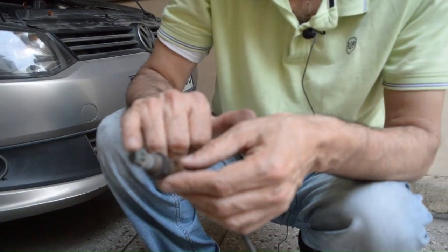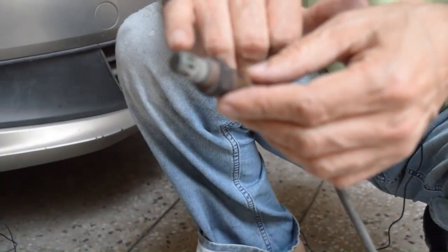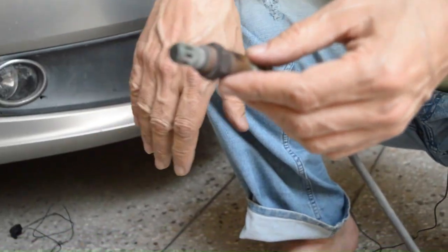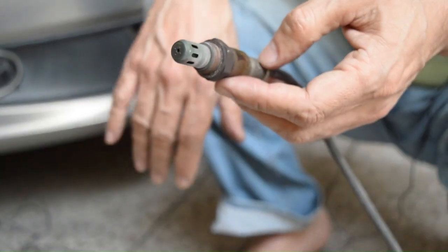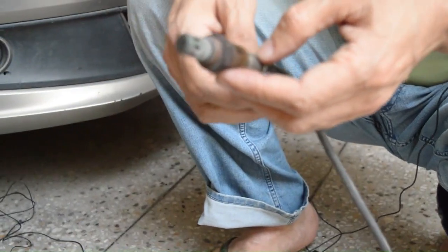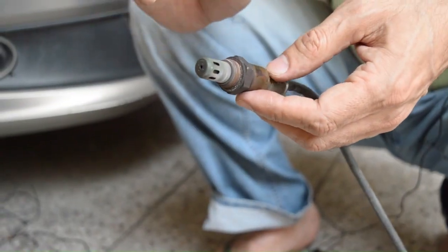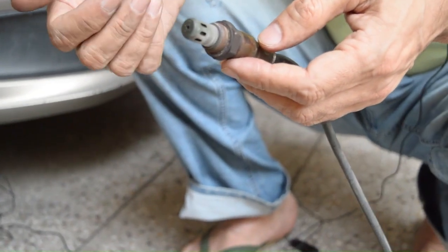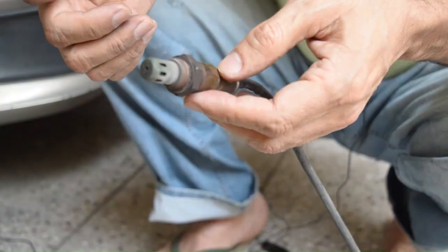The oxygen sensor works like this: it has a sensor here, and it measures the oxygen that is present in the exhaust after the combustion process. So the hot exhaust gas that is coming from the exhaust manifold passes through these holes, and that determines how much oxygen is present in the exhaust gases. If there is more fuel than oxygen, then the mixture is considered to be rich, and you will